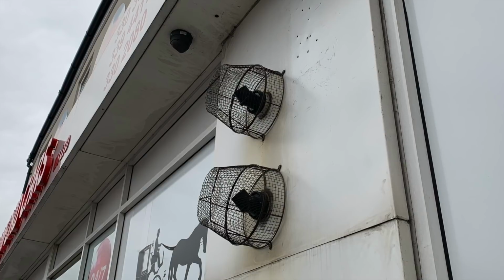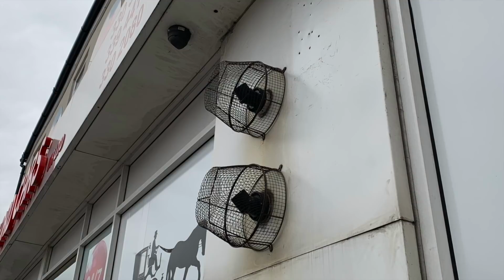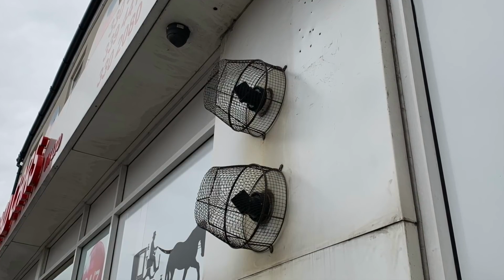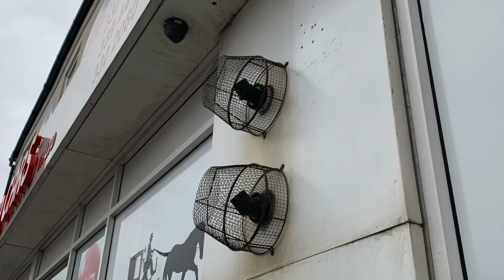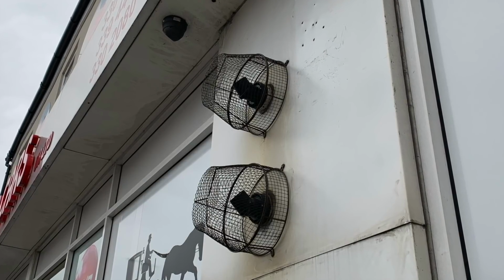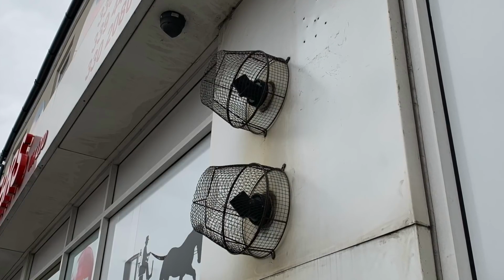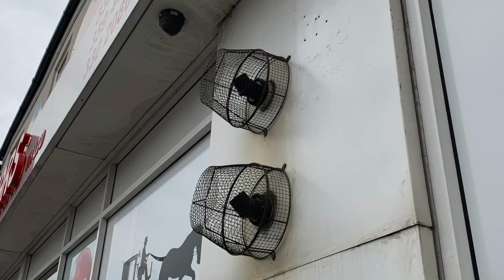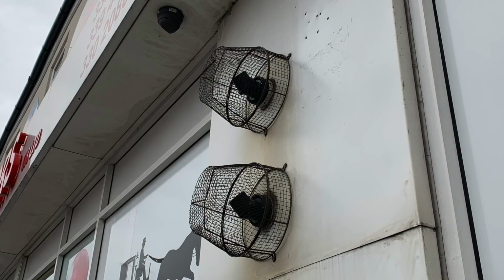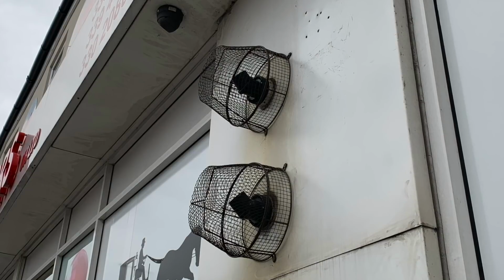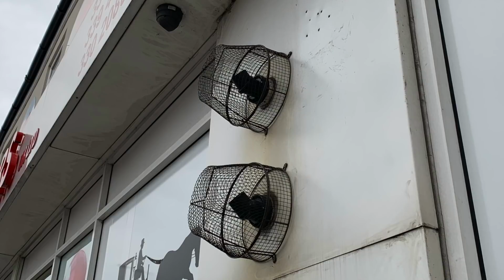So in this situation we'd have to get in touch with Worcester to see what Worcester say about the situation. But what I would be doing in this situation would be at risk, because the bottom flue could actually be affecting the top flue. But again, I would seek advice from Worcester just to make sure that I'm okay to at risk it. If they say it's fine, then it's fine. But we would need that reassurance from the manufacturer.